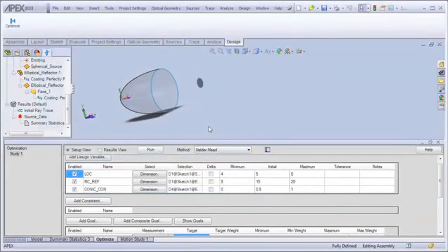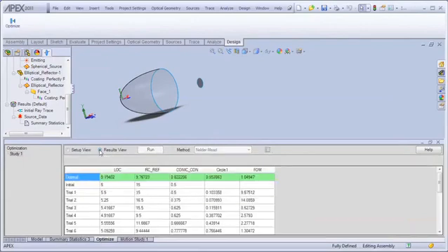When you are ready to view results, press the Results View radio button, and you will see your trial solutions listed, along with the various variable parameters and the figure of merit. At the top, highlighted in green, is the optimal solution. And if you click on that, Apex will automatically set your geometry to that optimal solution.